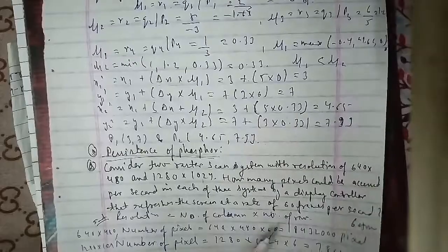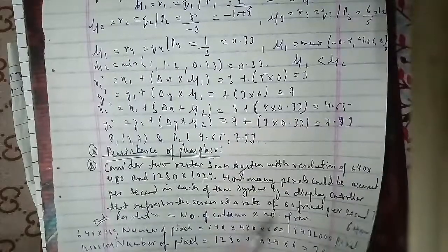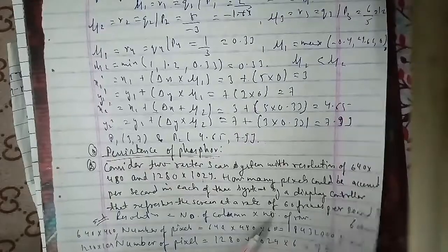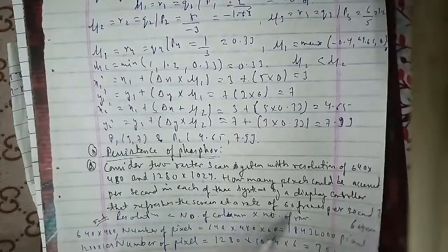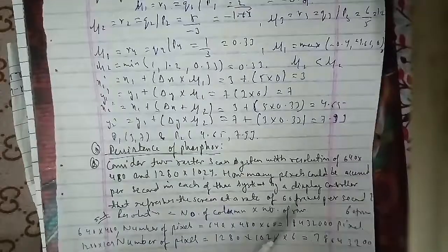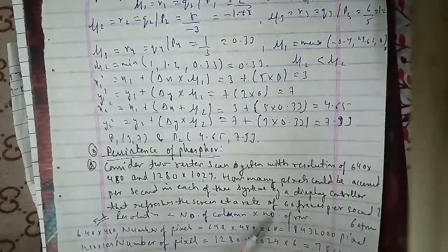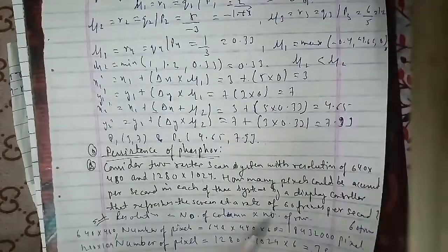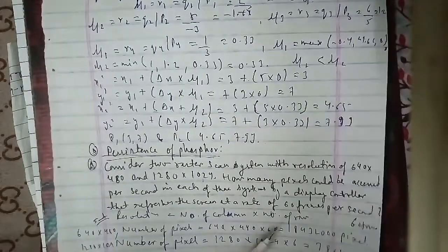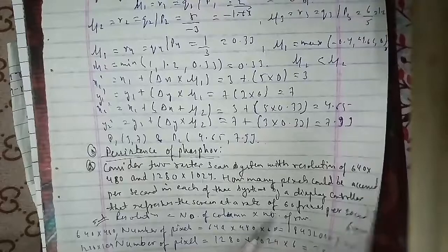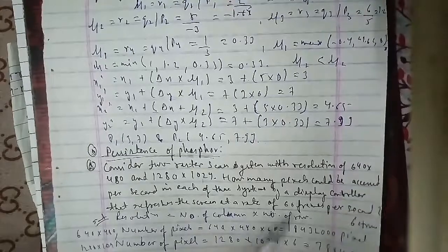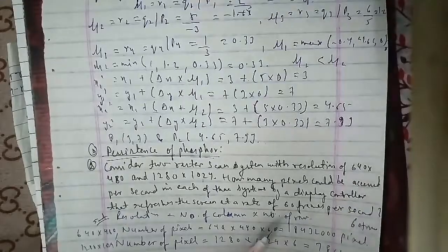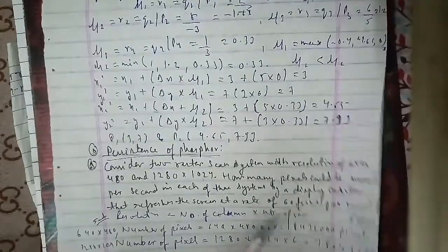The first is the window length, which should be greater than the effective length of the HRIR, and the window length can be effectively reduced under the minimum phase approximation. The second issue is window shape. Windowing the HRIR in the time domain is equivalent to convolving the corresponding HRTF with the frequency domain representation of the window function, and the simplest window is a rectangular window defined here.